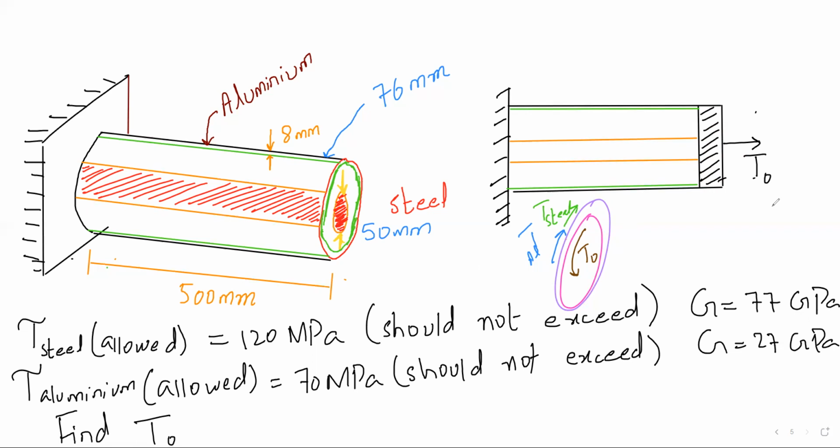I'm saying there is this cap. So when I'm putting the torque, both of them will resist or take the load of that torque. So this is the reason for putting that cap. Here the torque I am applying, both the steel and aluminum are taking chunks of it.